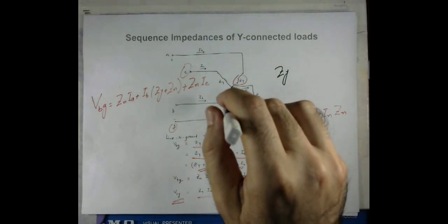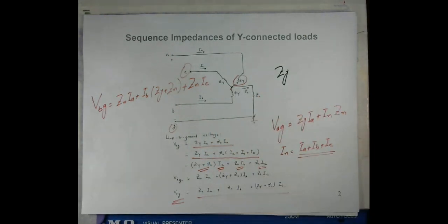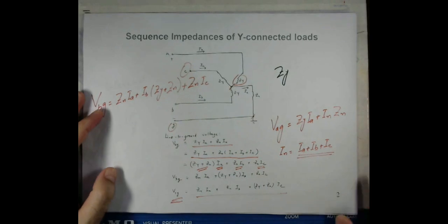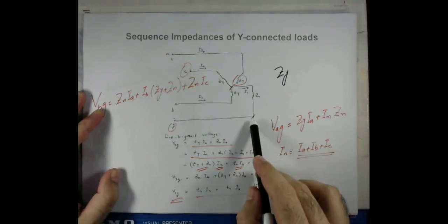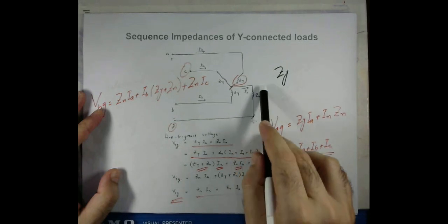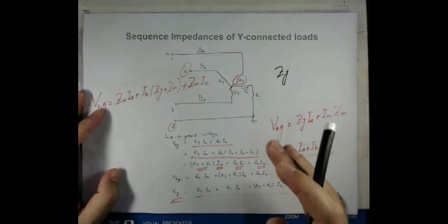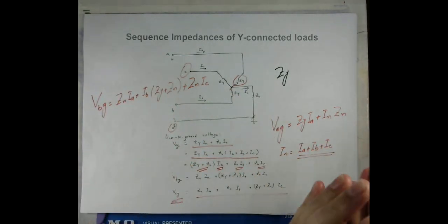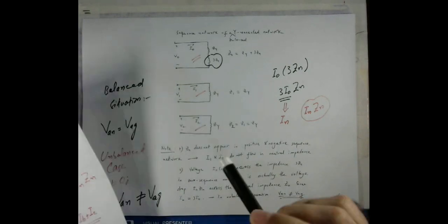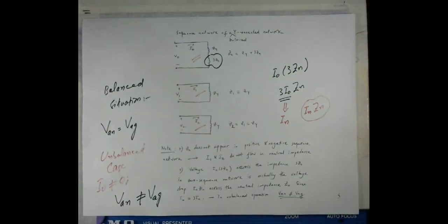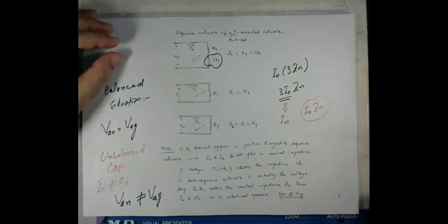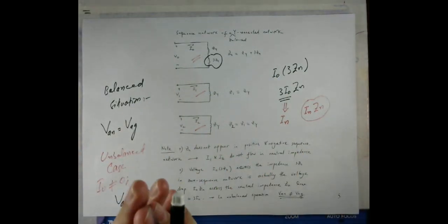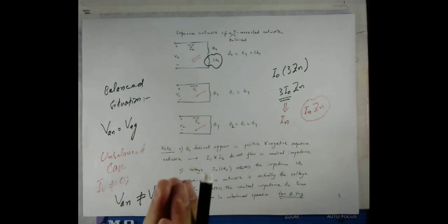So we took this particular case where we also considered that the neutral point of the load, Y connected load, is connected to the ground through the impedance Zn, and then we discussed the steps that are required for deriving the sequence networks, and the end result was that we derived 3 sequence networks, and we discussed that these 3 sequence networks are uncoupled networks.